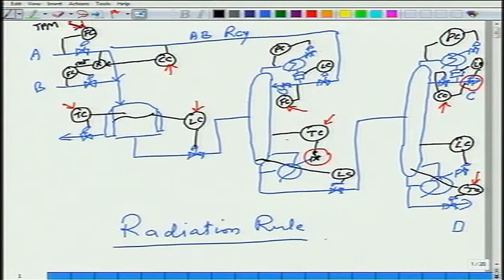Also, this column, the recycle column, should probably be run at flooding, at or near flooding condition. Why? Because that would ensure that my recycle is as much as possible. If recycle is as much as possible, then recycle is mostly A. I want to run the reactor in A rich environment. The richer the composition of A, the less the side reaction. Okay. So what that essentially means is,